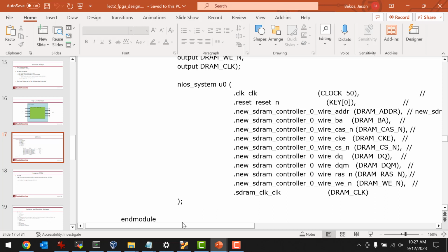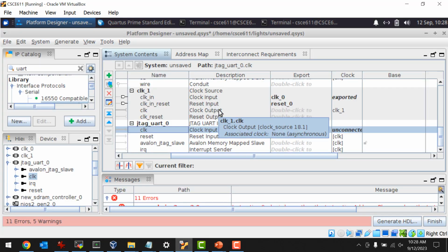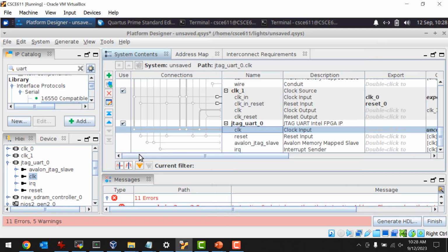So it's actually UART operating over top of JTAG, operating over top of USB. Right? So there's no pins for that. You just get that for free somehow. Okay, but normally anything you add in there that requires I/O would have a pin there, just not JTAG. Okay, that's it. So I haven't connected these guys, and this is the hard part.